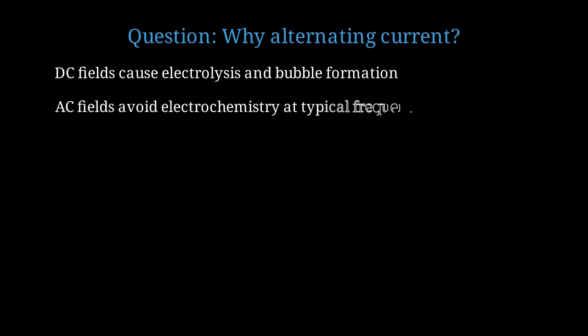Alternating current fields, especially at frequencies above 1 kHz, avoid electrochemistry. The field reverses before significant charge transfer occurs. This is why ACEO electrokinetics dominates modern microfluidics.